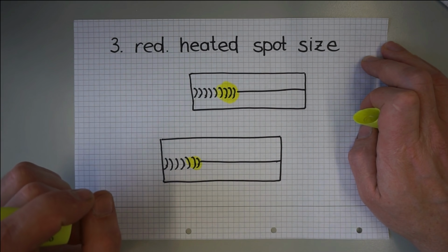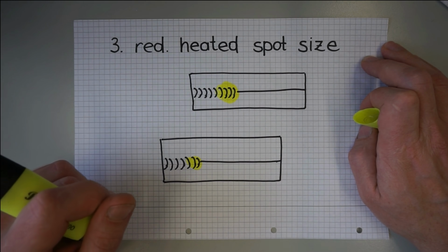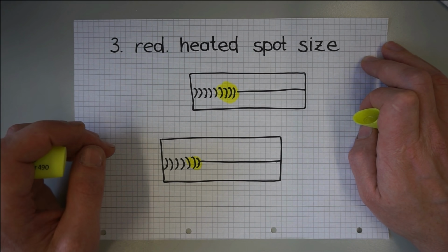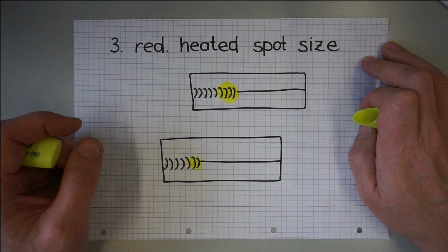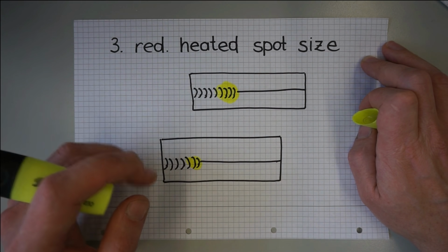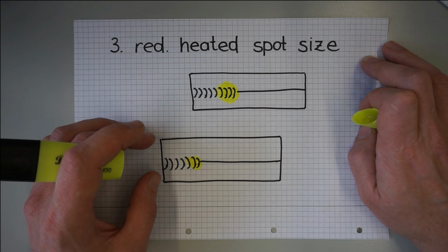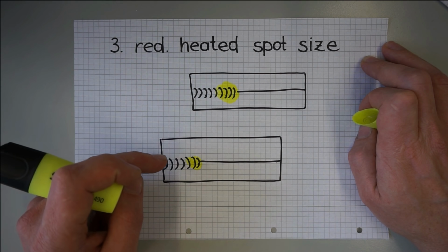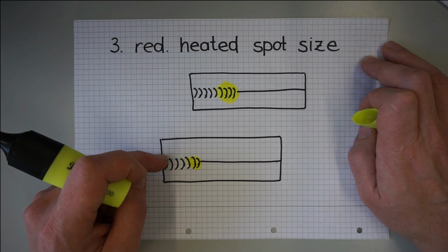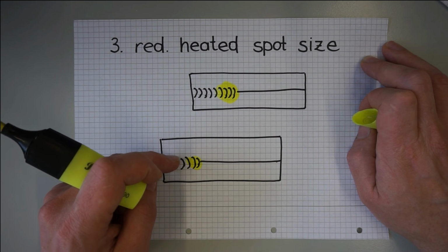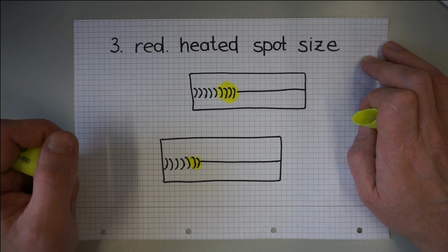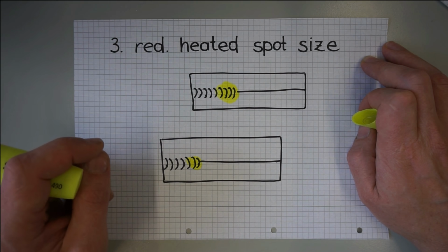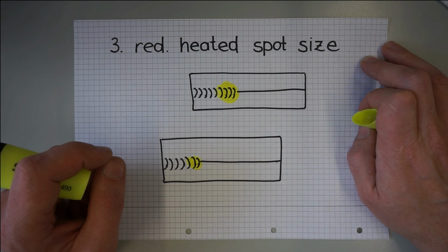Even for a given welding process, say TIG welding for example, there are techniques to reduce the heated spot size. Pulse welding for example. This is a very smart technique which exploits heat conductivity's need for time. By pulse welding, we repeatedly create a melt puddle of given size in a short time span with high current, after which the machine switches to a lower background current, during which we travel the torch. This limits the amount of heat which is naturally carried away by the workpiece to form the heated spot.